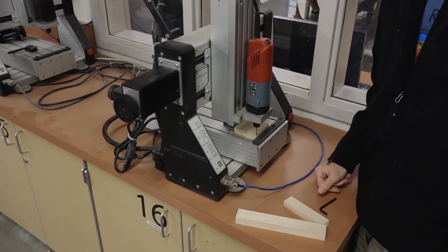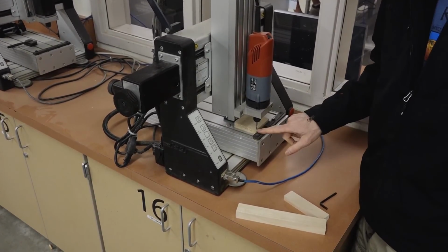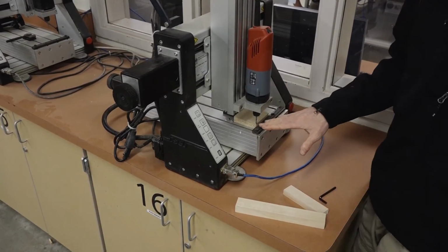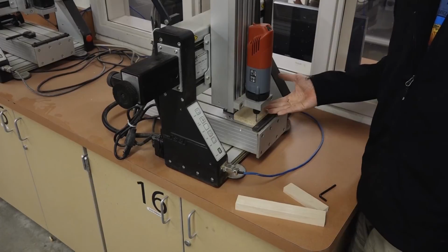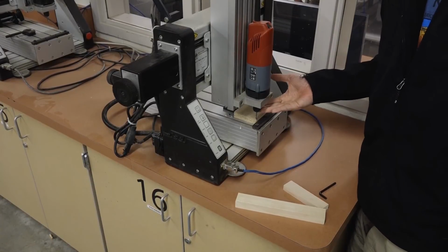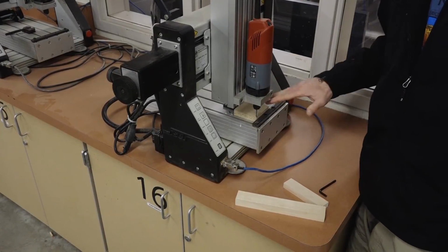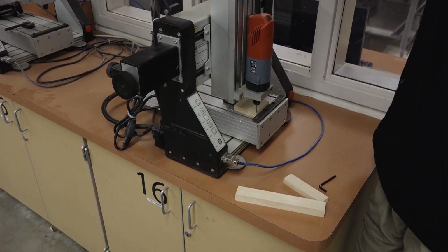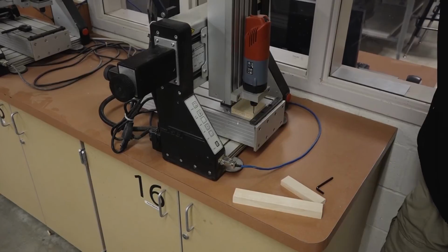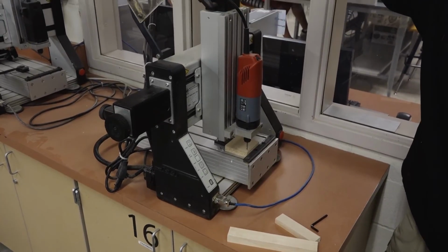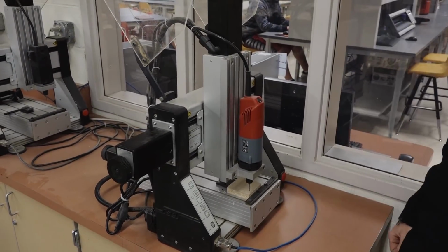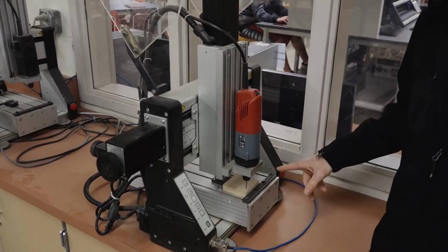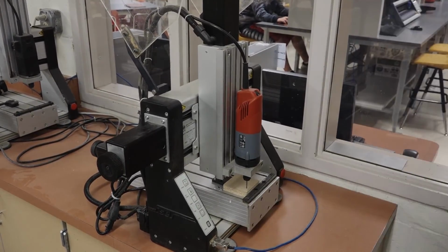Usually what I want you to do initially is you're going to have this up in the air. If you know you're going to mill down 1/8 of an inch, I want you to raise it up a 1/2 inch or something. I want to dry run it in the air first to make sure that it's not going to damage anything. So what I would do is just raise this up 1/2 inch or so, and now we're going to dry run it in the air. Let me turn the power on so you can see what that looks like.